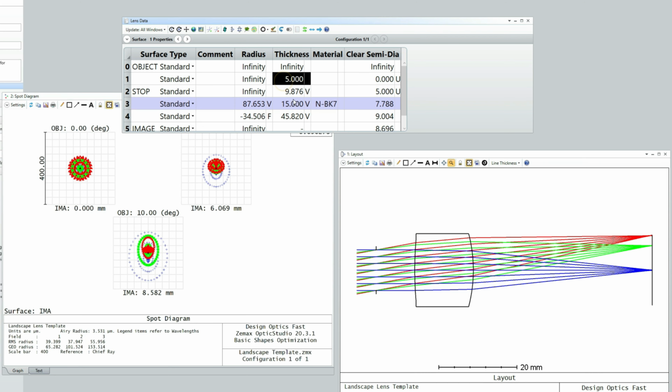You can see that the center thickness has moved to being exactly 15 millimeters. And thickness is a weak variable. We'll usually go to the maximum allowed value. Designers often simply set the thickness of a lens to its maximum allowed value and don't optimize it.